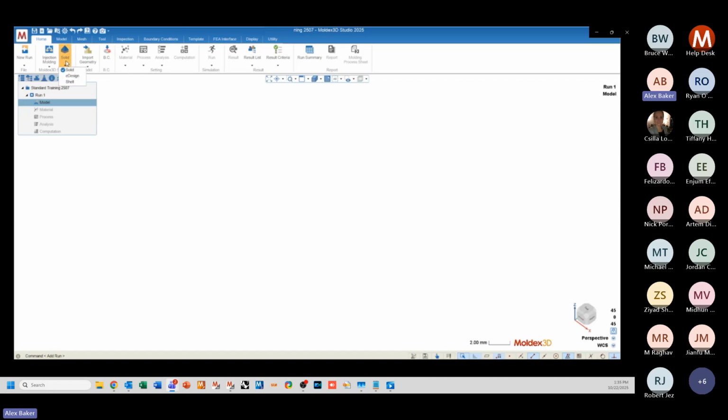To the right of that is our meshing style. We have 3 different meshing styles in Moldex3D. Solid is what we'll be using 99.95% of the time. It's pretty much the standard meshing style for Moldex3D at the moment. And so this is what we call the boundary layer mesh type of meshing method. Below that is eDesign. This is the voxel type of meshing method. This will be used if we can't create a mesh in solid.